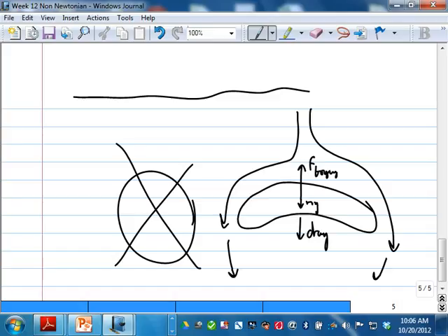And the other thing is, inside here is not solid. It's a vapor. It's a gas. So it tends to circulate also. This circulation of air inside the bubble tends to assist them in rising up, make it easier. So the drag is not so high. Because if you are solid, here will be a wall, you have boundary layer and all that kind of thing. But this is not a wall, this is just an interface. The air inside here will recirculate, and that will help the bubble rise.